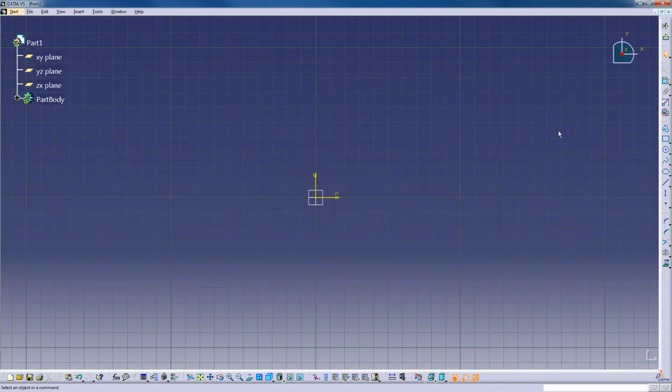Okay, so we look over here and we say, well, what do we want to do? We want to make, how about a circle, right? So this is pretty standard issue stuff. So you pick the circle, and when you come out here, what you're going to do is click to start it and then click to end it. A lot of regular graphic programs will have you click and drag. If you're used to that, that'll probably take a little bit to break that habit, right?